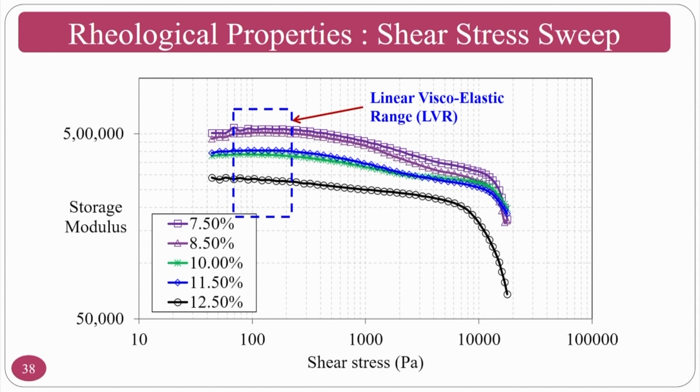In this experiment, we are changing the shear stress and observing the storage modulus. We have kept the sample and it is continuously moving with respect to the shear stress change. If you are changing the shear stress, all the graphs follow approximately the same trend.